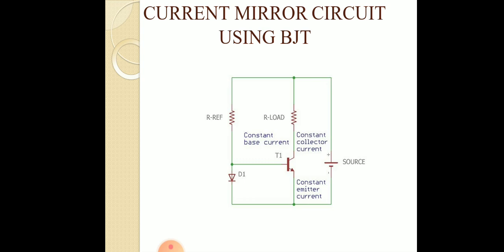In this voltage to current converter configuration, simple negative feedback across the transistor converts the voltage to current converter properties to an opposite logarithmic current to voltage converter. Generally, the negative feedback is done by joining the base and the collector of the transistor.